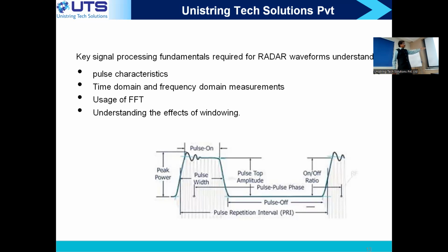So you will have a pulse width and you have PRI, two important words. Pulse width is nothing but the time your energy is on, isn't it? In your radar course, you must have done some duty cycle calculations. Duty cycle is nothing but pulse width divided by PRI. So just keep all this in your mind. We'll go to the next slide and see the impacts of this.